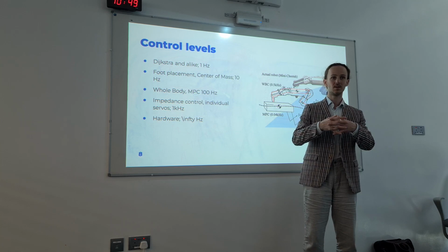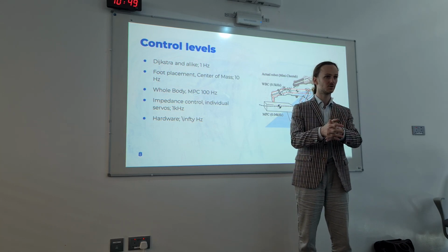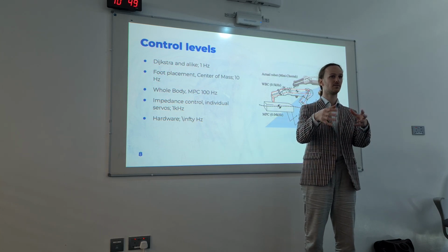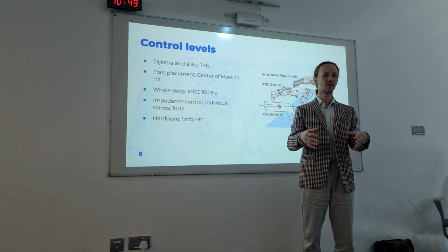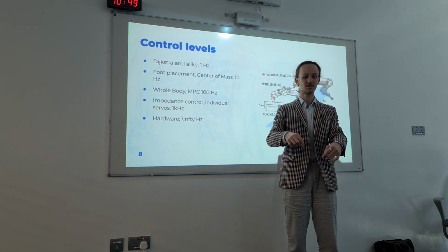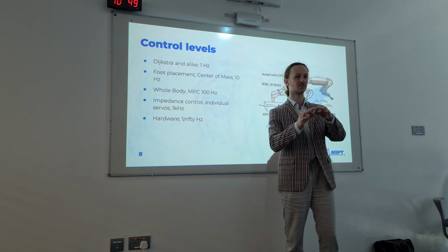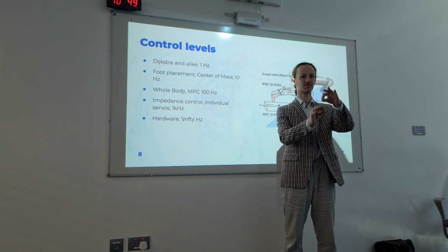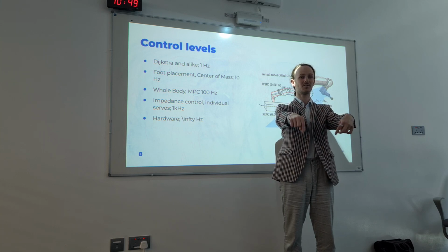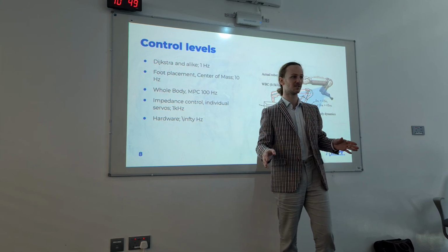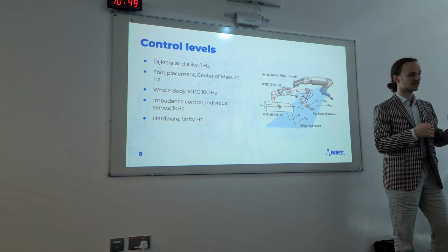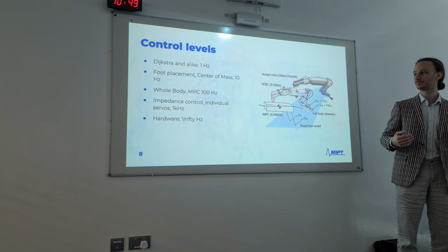So the state vector here should include more coordinates, z coordinate included, the velocities, maybe the angles, and also we have to keep an eye on the foot placement, but legs are considered as massless rods that instantly change the place where they are, where they support the body. So this is still an abstraction, but it's just closer to reality, to the real dynamics of the reality.